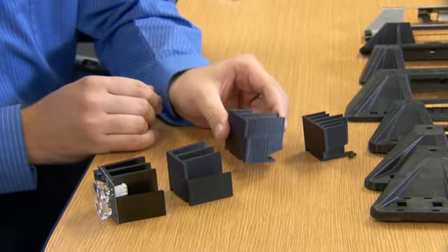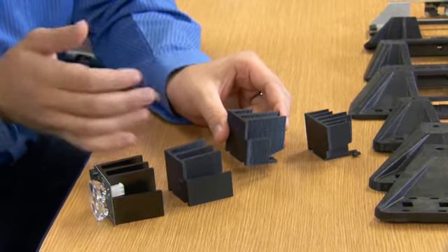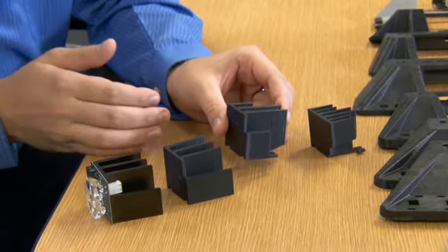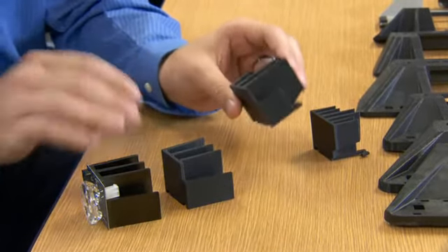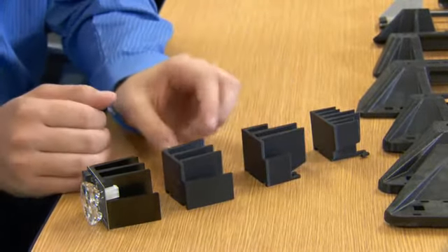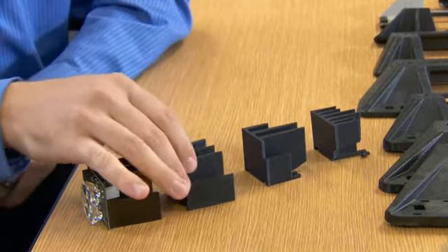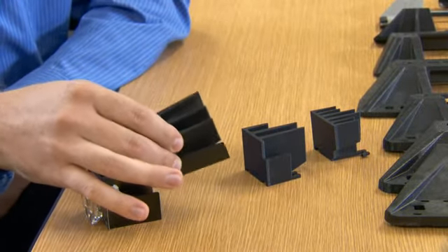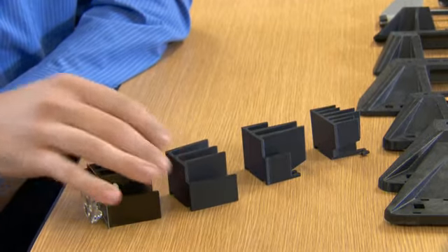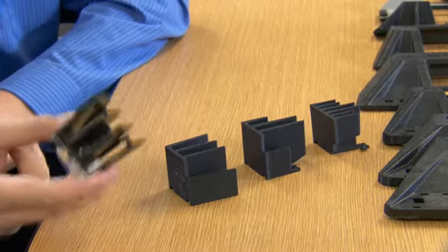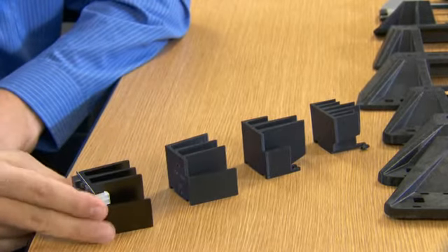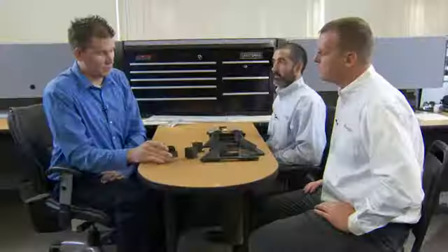We spaced the fins out because of SOLIDWORKS flow results. We achieved lower temperatures. So by spacing the fins out, we got lower temperatures, and then finally, just based on tool design and overall aesthetics and fit, came out with a final, more refined design that used less material and achieved better results overall until we got to the tooled final production piece and achieved a lot cooler temperature, so it ran more efficiently and actually used less material too.